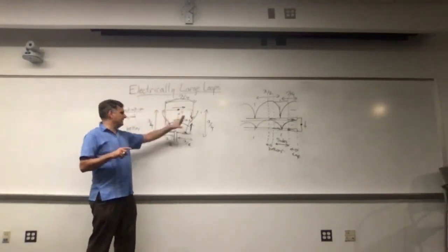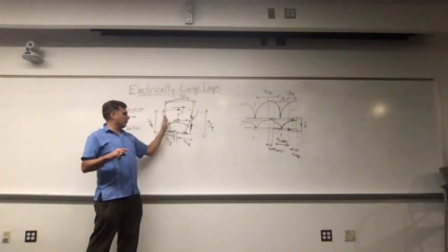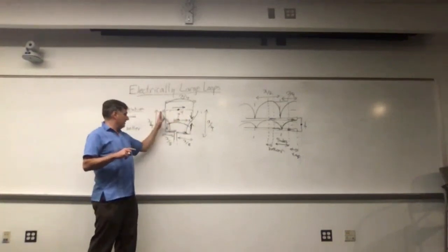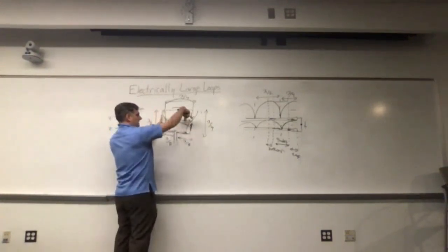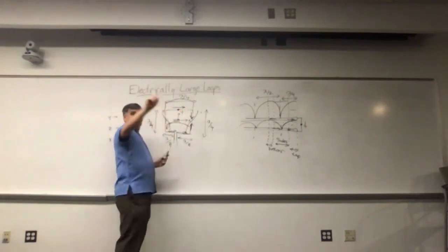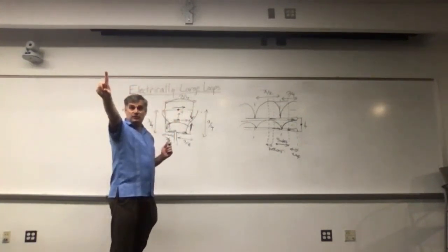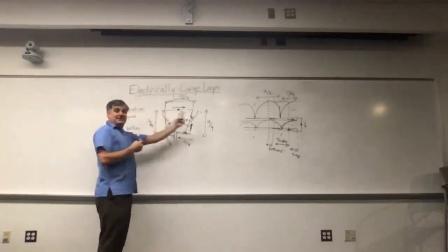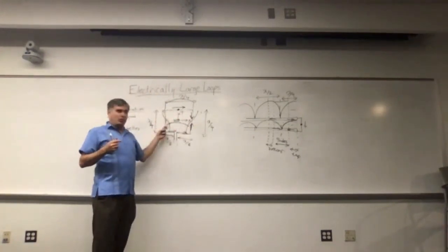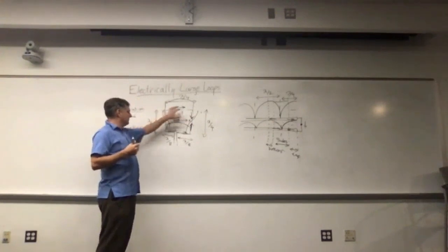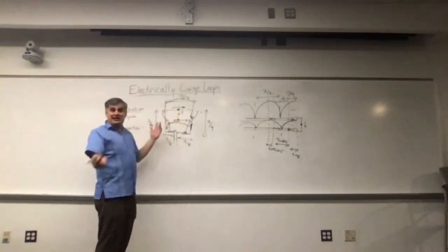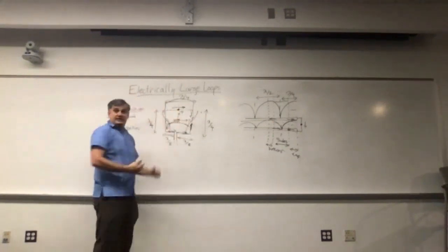It's not going to be completely destructive because they're only a quarter wavelength apart. But it's the mirror image currents this direction. So this polarization in Z is not going to make any contributions in this polarization because they're the opposite phase and they have an inflection point. So this cancels with this cancels with this, and if there was any residual, this would cancel with this.